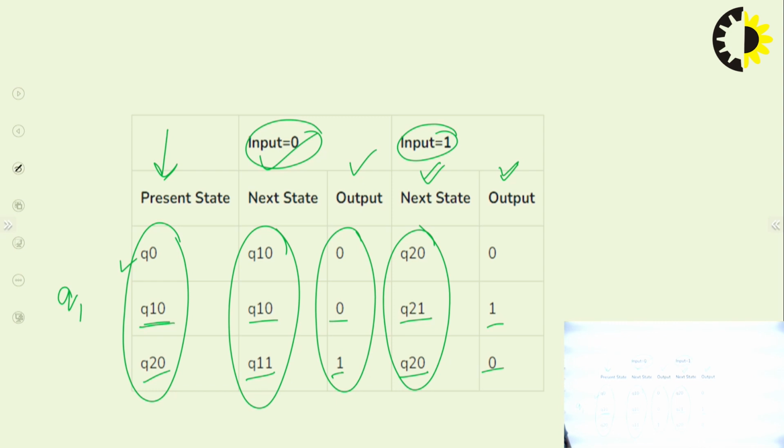And then we have to convert the format of the machine, because Mealy machine depends on both present state as well as input, and Moore machine depends on only present state. So the format of table is different in different cases, and the method to write the output is different. In case of Moore machine, there is no need to worry about the output. We have to go to the previous table and check the output for present state, and then write the output for that next state, and so on. This is the whole about Mealy and Moore machine.